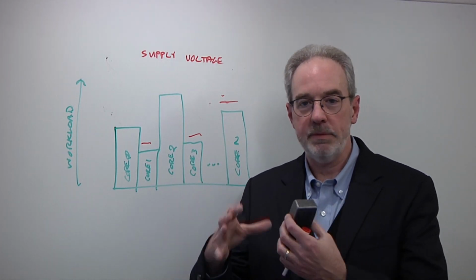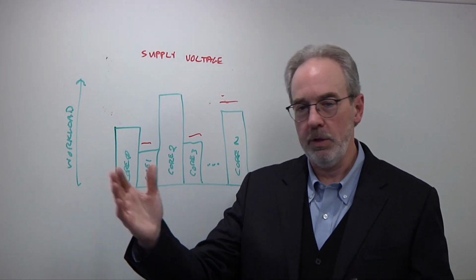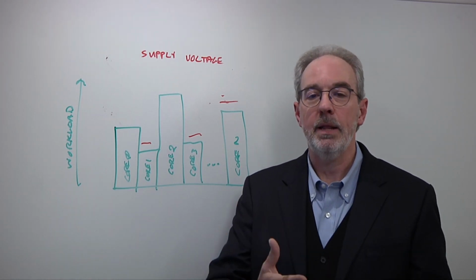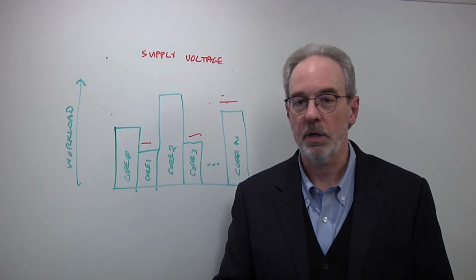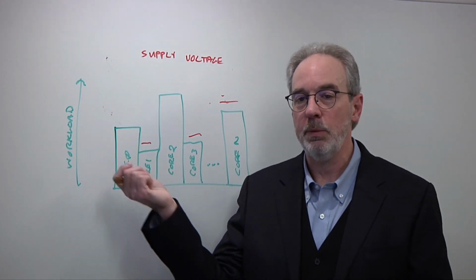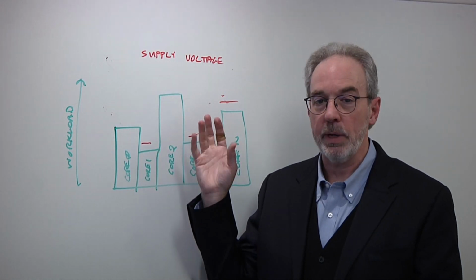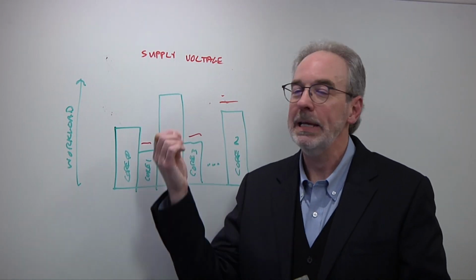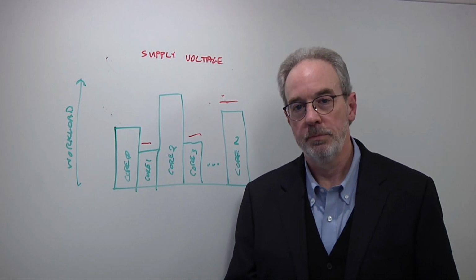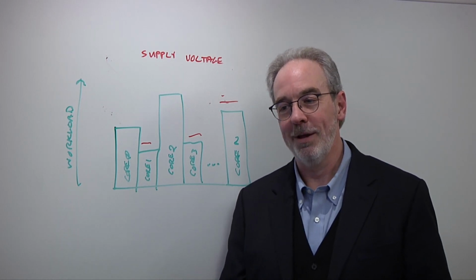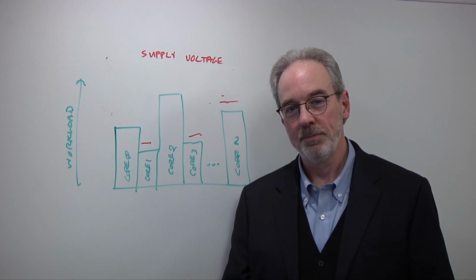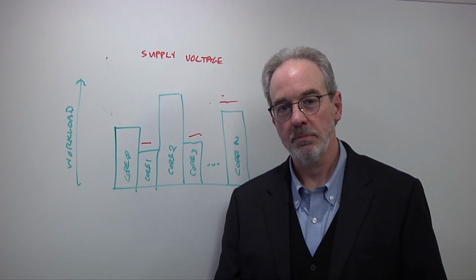Similarly, designs have tended to be very closed loop. You design it and then you hope it works. Now we're seeing more embedded sensors. Those sensors are driving data that feeds the analytics engines of silicon lifecycle management. The ability to see inside your power grid to see what's happening, and these embedded voltage regulators can also provide that telemetry, is a key aspect of understanding what to do and when to do it. You also don't have the margin that you used to have in the past. And you see some of the large designs that are going on by the systems companies, something like 45% of all the leading edge designs.